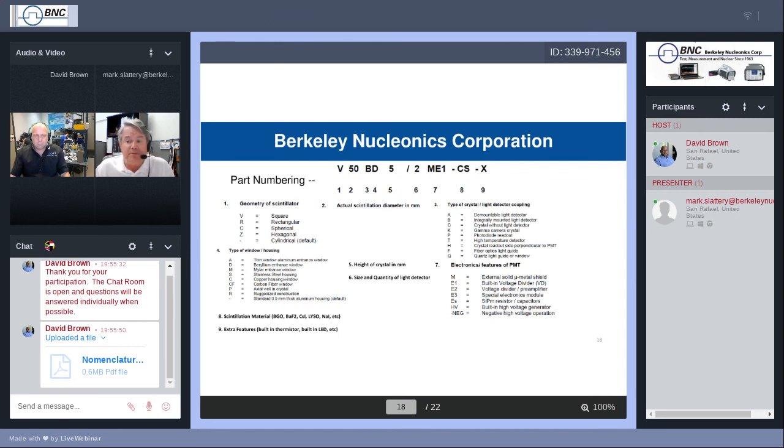Do you need a negative bias? And this is important, particularly if you're interested in fast timing. If we are talking about something in the megahertz, you'll need to have that bias voltage in the negative. It's almost an entirely different topic unto itself, something that we can't go into detail here. But this is something to consider, and we will remind you if you're telling us that speed is very important.